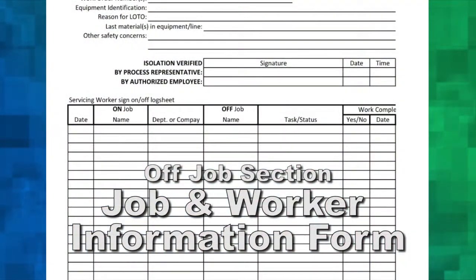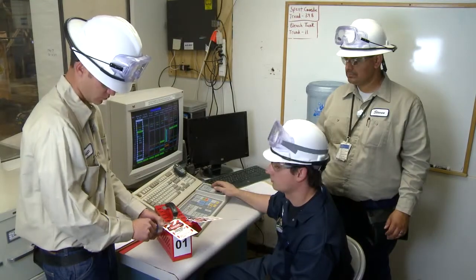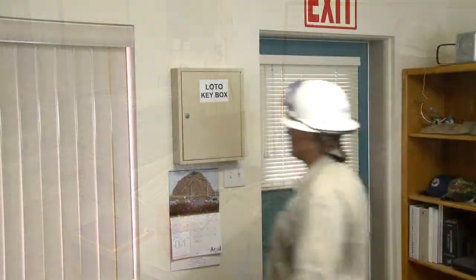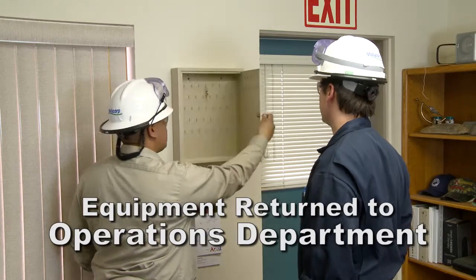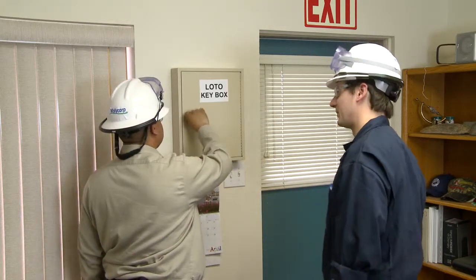The servicing representative fills in the off-job section of the LOTO Job and Work Information Form. The servicing representative will then remove his lock and tag from the lockout box. At this time, the equipment has been returned to the operations department from maintenance. The authorized employee retrieves the key from the LOTO key box and returns it to the process representative.